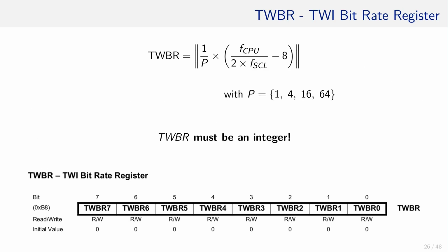If the MCU is a master of the I2C bus, it needs to generate a clock signal for the SCL wire. Like the transfer rate configuration in UART, the frequency of the I2C bus needs to be configured as well. The frequency is computed by this formula.